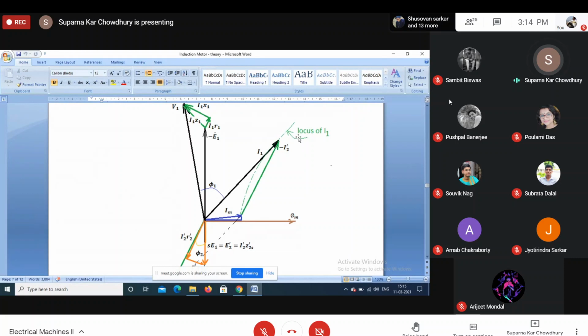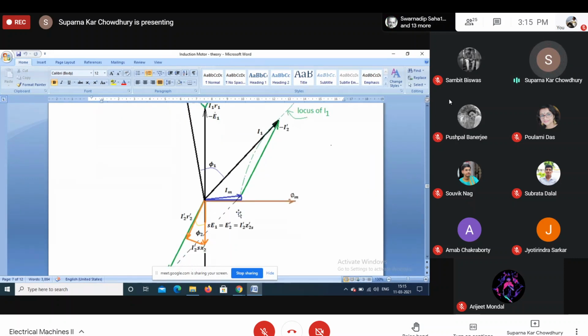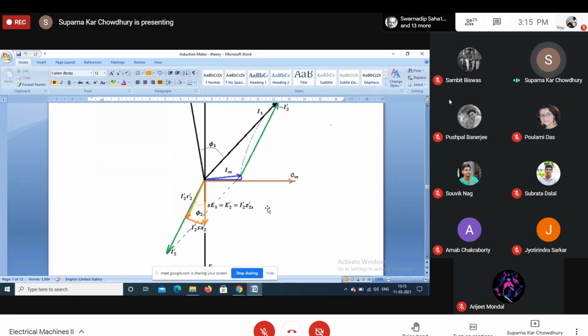That is okay, but whichever concept you follow, follow the same one and explain the phasors. So besides this, what will be the other current? Now in the secondary, under no load condition, the slip is very small. So basically the current which is flowing in the short circuited secondary is very small, so it is negligible. If we neglect that component, this is the no load current.